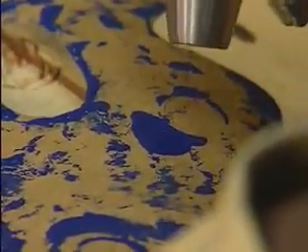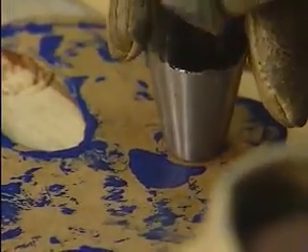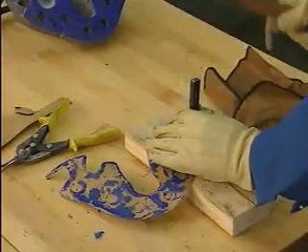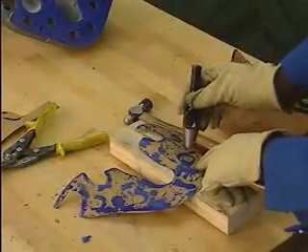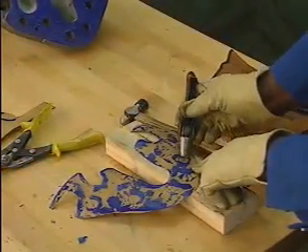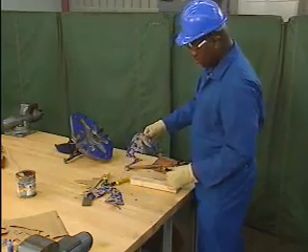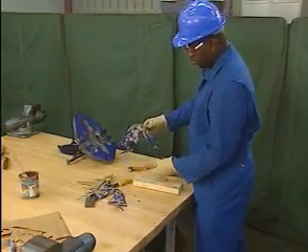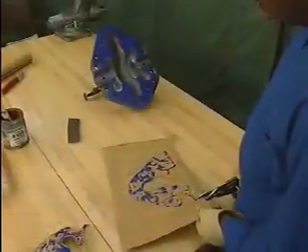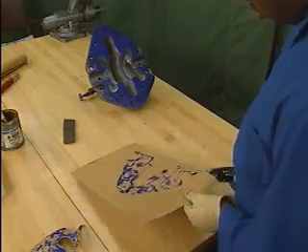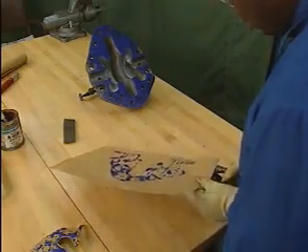The mechanic places the gasket on a piece of wood and positions the hole punch over one of the hole shapes on the pattern. He then strikes the punch with a hammer to make the hole. The process is repeated for each bolt hole in the pattern. Once all the bolt holes have been punched out, the gasket is ready for installation. The mechanic then cuts the other gasket for this pump following the same procedure.